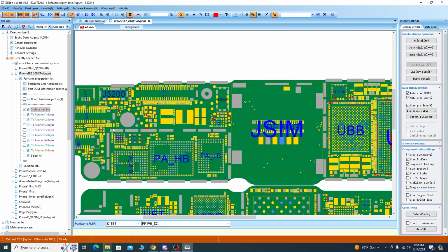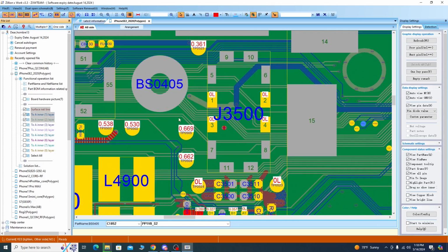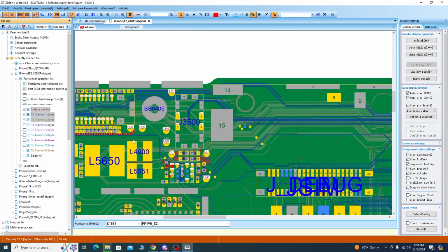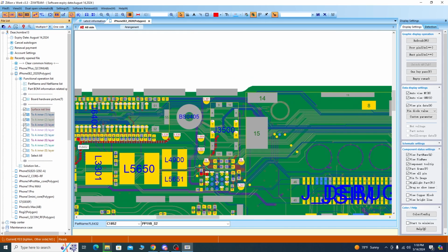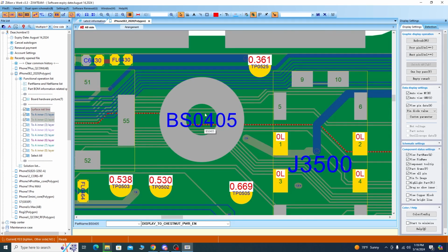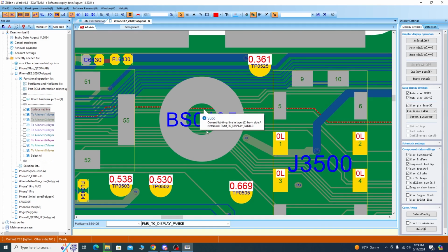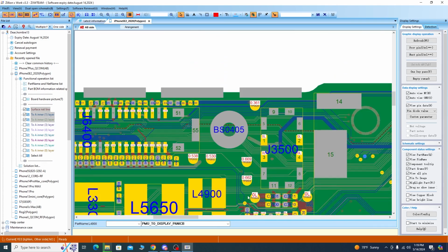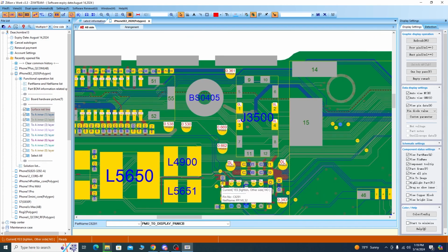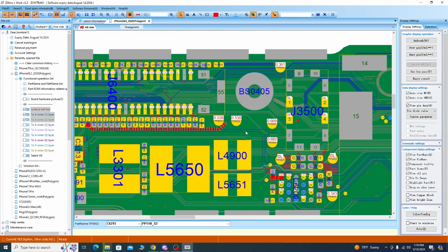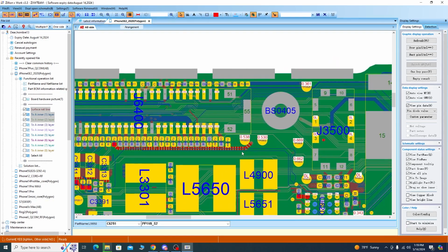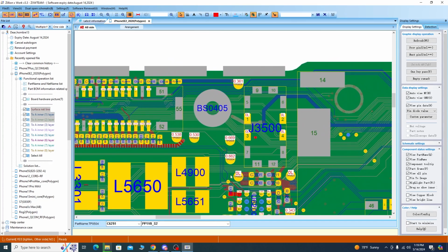So let's see if I have, yeah, I do. I have the layers here. So it's not the first layer. It looks like it's the second layer possibly. Still actually don't see it. Yeah, very interesting. I'm not seeing a direct line under here, but the board views aren't always correct. It has to be there because that's where I'm seeing the heat.